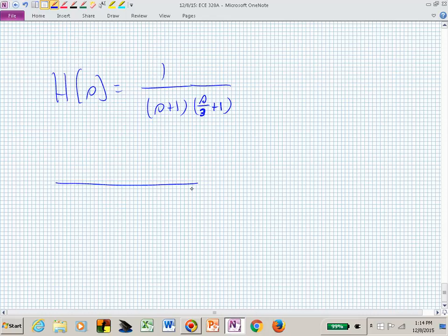But what's the Bode plot look like? Well, we're flat until we reach 1. Then we're going down at 20 dB per decade, but is 3 a decade beyond 1? No, but it's a little more than an octave, isn't it? And how far is an octave? 6 dB. So at 2, we're at minus 6. And at 4, we would be at minus 12. So we're between minus 6 and minus 12 when we reach 3. And at 3, we now fall off at 40 dB per decade.